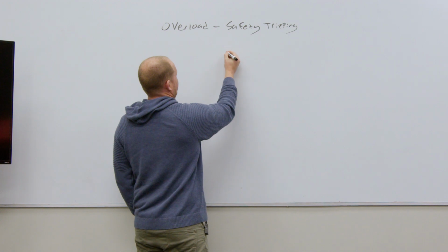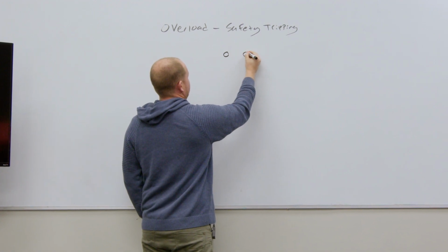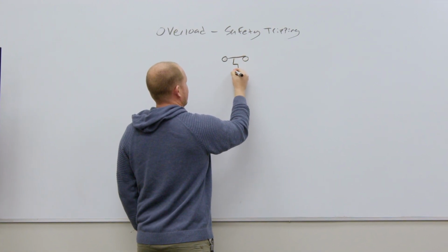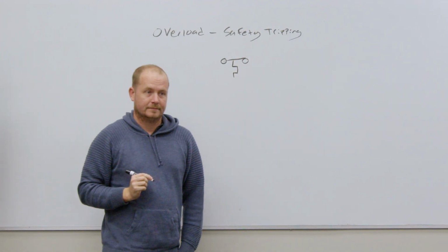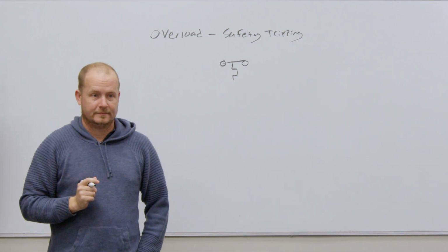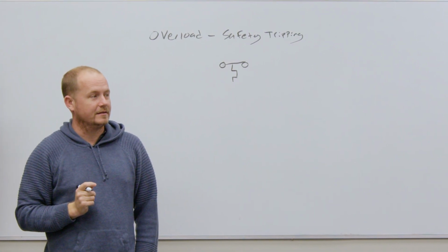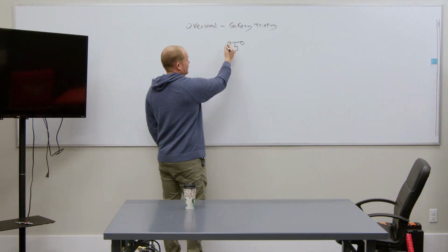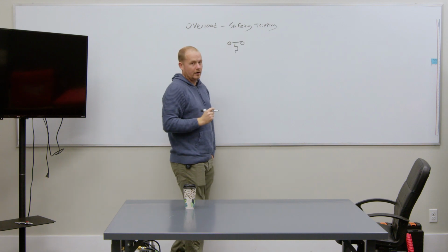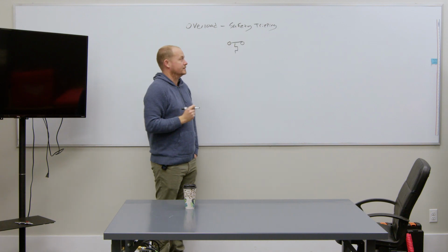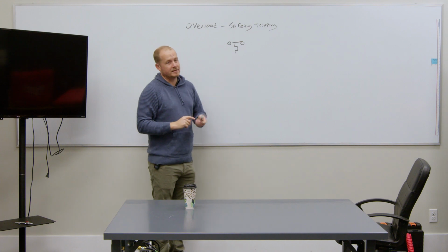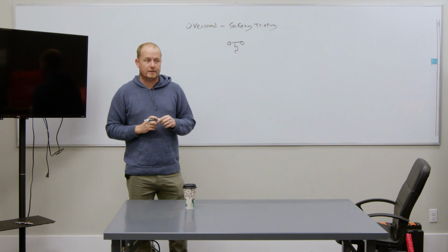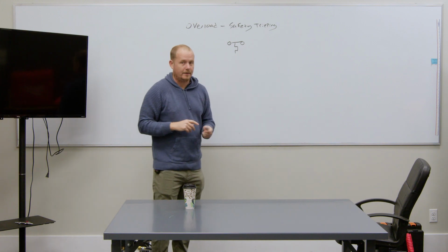I'm just going to draw pictures while you're thinking. Let's get some theories here. Anybody know what that is? Switch. What type of switch? Safety switch. Hold on. Is it normally closed or normally open? Normally closed. Open on rise. Temperature switch. So this is your traditional good old-fashioned thermal overload. So what makes a thermal overload trip? Temperature. It gets too hot, right?